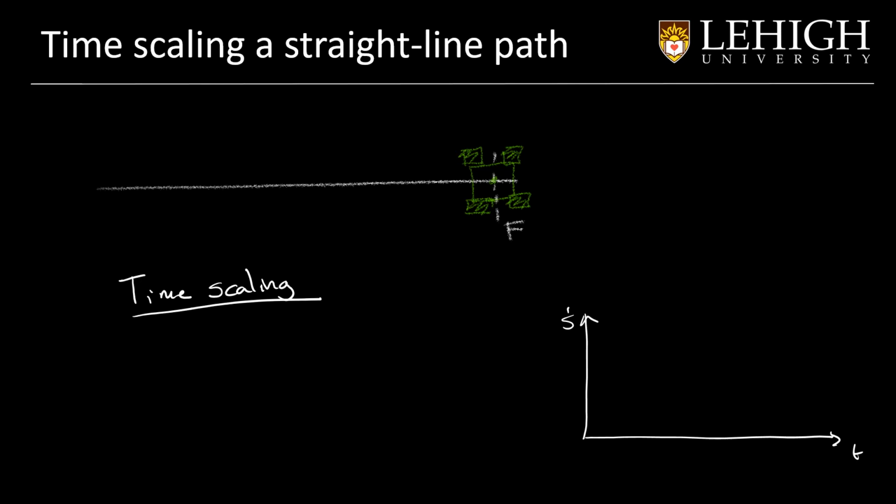One way to do this is called the trapezoidal profile, where we apply a constant acceleration, and then when we reach a desired velocity, we keep that velocity until a point where we need to decelerate. However, that trapezoidal profile requires a drastic change in the acceleration.